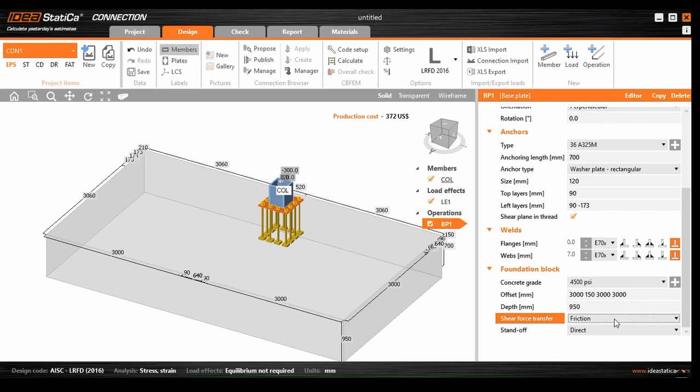So in the next part, we should choose how the shear force is conveyed to the concrete. I choose anchors here. Okay, well, so far so good. It is well done. So far we assigned the column and base plate geometry. We defined anchors and the geometry of the anchors. We defined the dimensions of concrete block. And next we are going to add some stiffeners to the joint.